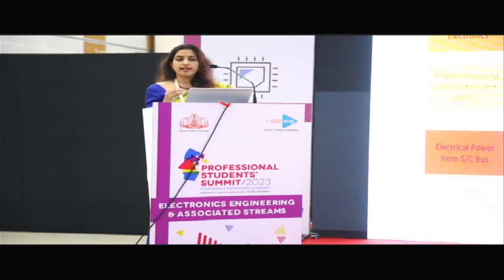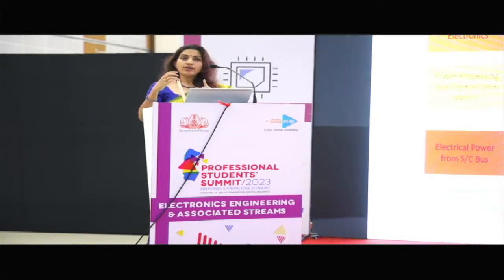So how this SPT works is that basically there is a cathode and an anode. The cathode has a heater, and we send electricity through it and generate high current. The heater generates a lot of electrons by virtue of thermionic emission, and the electrons come out. Now we have an anode, where we give a very high potential in the range of 350 volts. When the electrons come out, they see that high voltage and try to rush through that high potential. But in between, we give a high impedance by virtue of a magnetic field, and the electrons get trapped in that. Now the electrons circle there, and by virtue of the Hall effect which you have studied, there will be a Hall current, and that is why it is also called a Hall effect thruster.